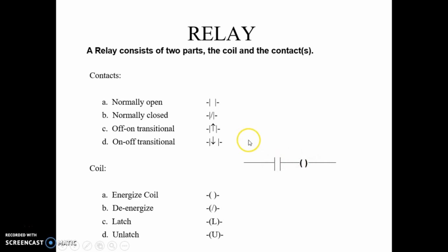So in ladder logic, from the left side, first input should be written and then after output should be written. So this is normally open contact of the status of the condition, and this is the output. So this is normally open contact and this is the output. Whenever this contact is energized, it makes the contact with the circuitry and delivers the output to the coil.